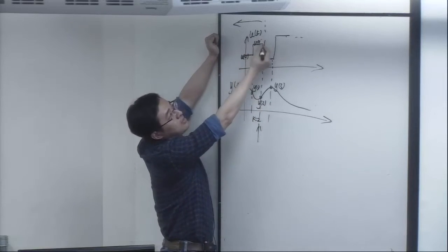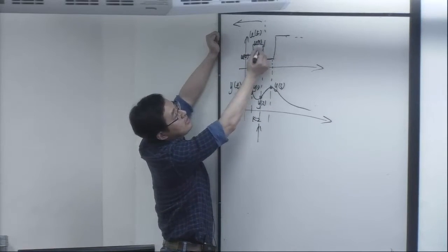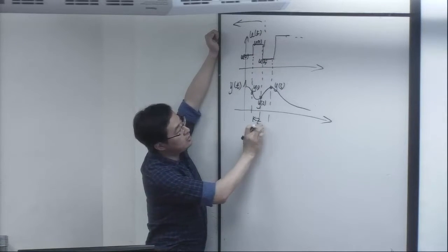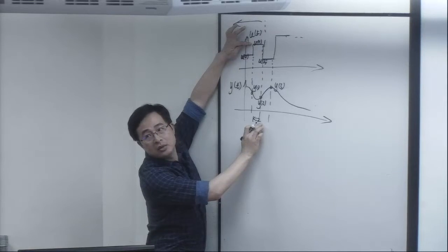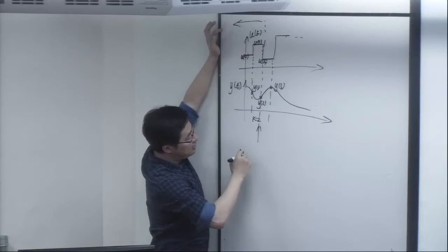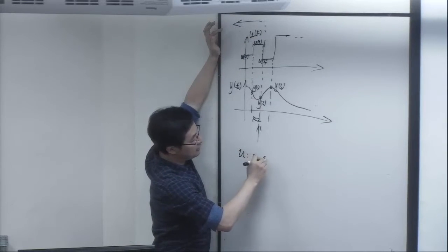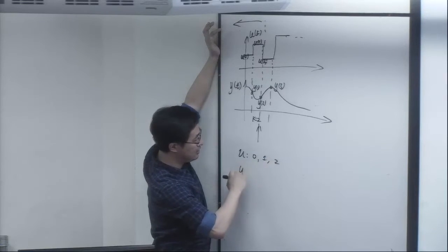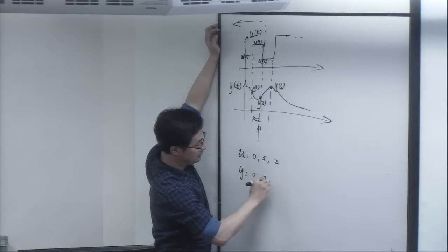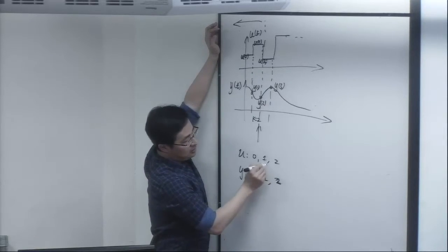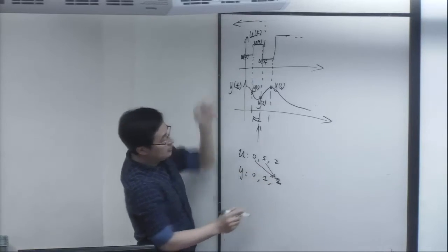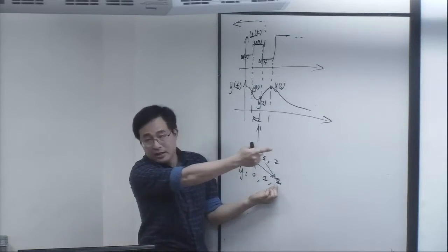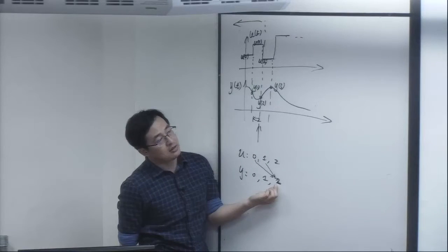So because I'm using a zero order hold, at time k equal to 2, only the input up to time k equal to 1 actually matters. So there is an intrinsic step of delay in the effect of my controls. It is exactly expressed in that transfer operator over there.